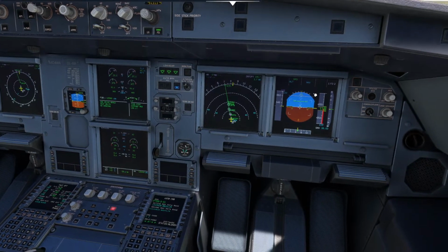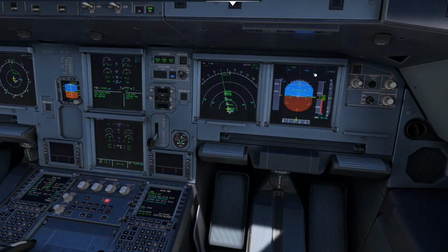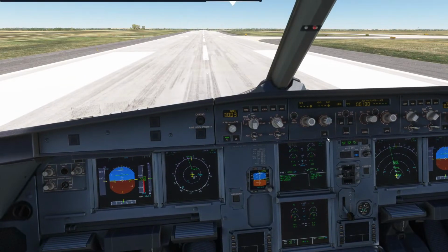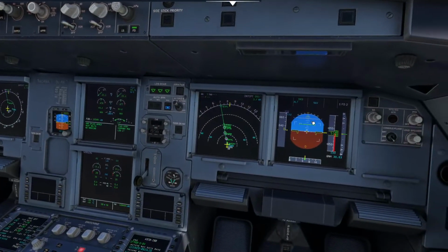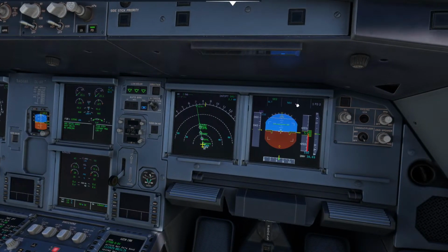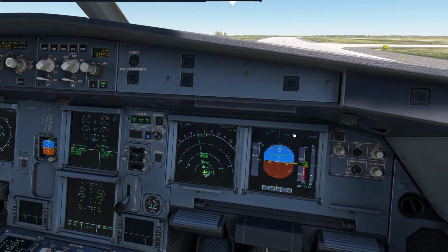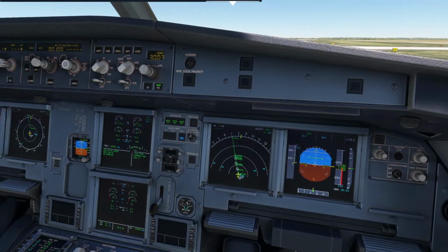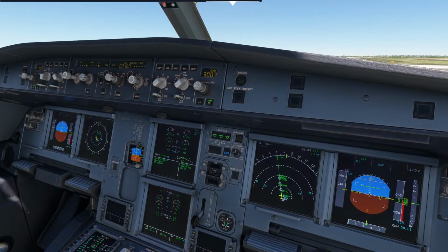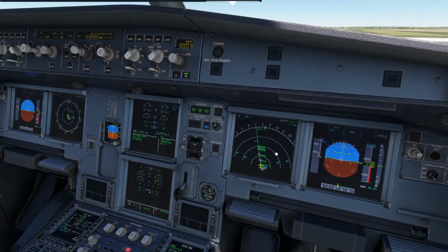So now you're going to see here on the screen, you have SRS, altitude, and nav. What I'm going to do is make sure that those are the right FMAs. I should have nav as blue, which means it's armed. Altitude, we'll just put 230 in here, our top altitude of 230, but then we'll put it in managed mode, which is pushing it inwards. Speed managed mode as well, and we're ready to go.